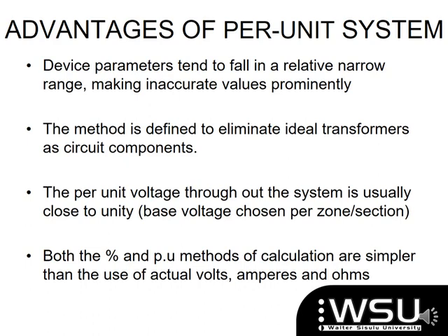So we always utilize the per unit or sometimes the percentage method for us to do our calculations, making them simpler than when we use our actual voltages, currents, or amperes and ohms in your impedances.